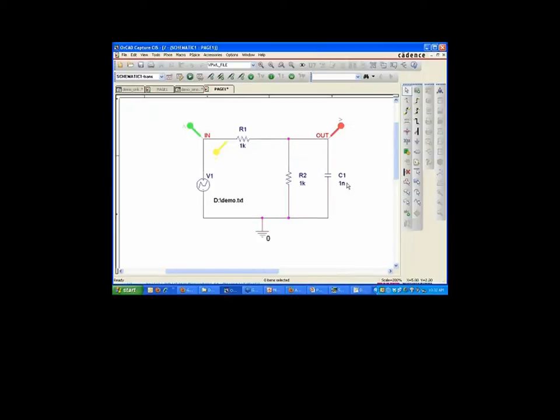So we prevented you from doing something like this. If this was your design, and this is the default behavior of OrCAD Capture from version 15.7 to the current, what it'll do now is if you try and do something silly like that, so if I try to move that component, I'm essentially going to be shorting a bunch of stuff. So notice it's not letting me actually put that down there. I'm actually clicking my mouse here. It's not letting me put that down.